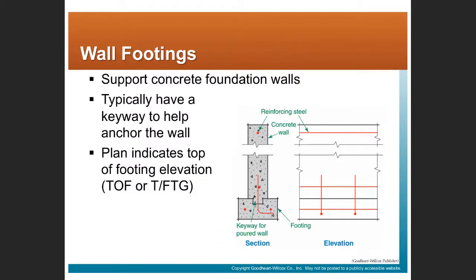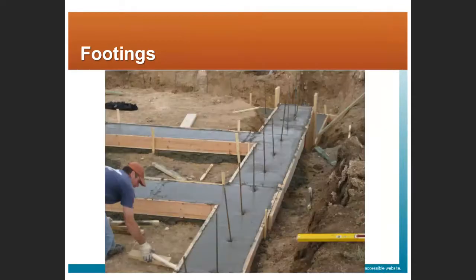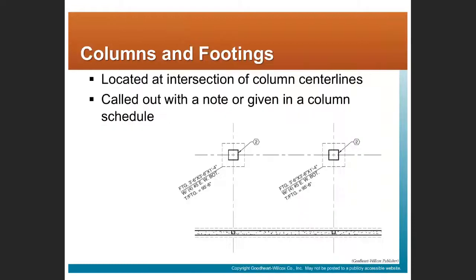Right, again, cutaway, a foundation wall, reinforcement, keyway that locks the two things together. Quite often the footing is poured separately from the foundation wall. Right, you see here a picture of a footing with the rebar coming out of the footing being ready to pour the foundation wall.